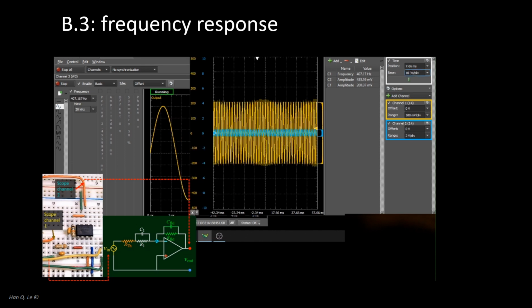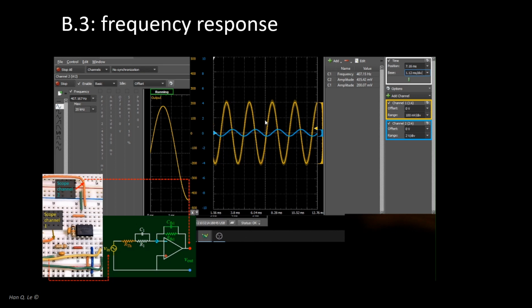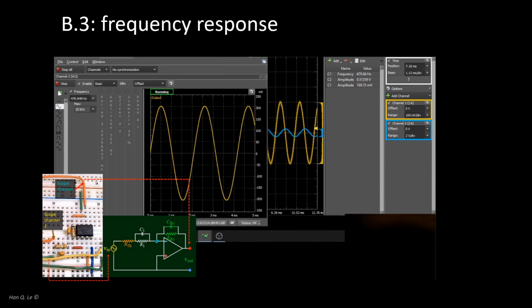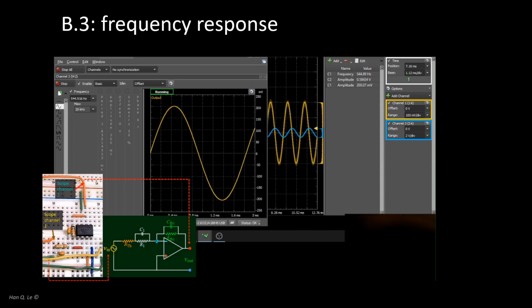The outcome of this step should include Bode plots. Please follow the instructional video if necessary. The first sanity check is to look for the 90-degree phase shift expected for the derivative of a sinusoidal.